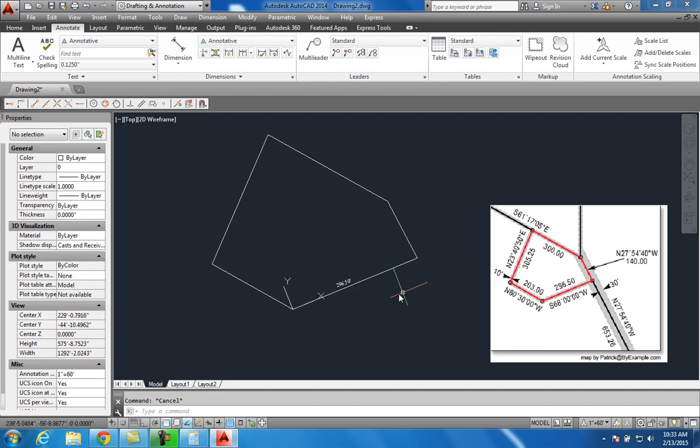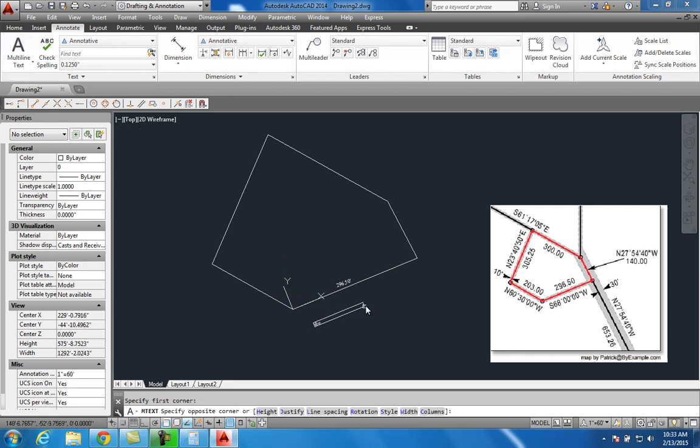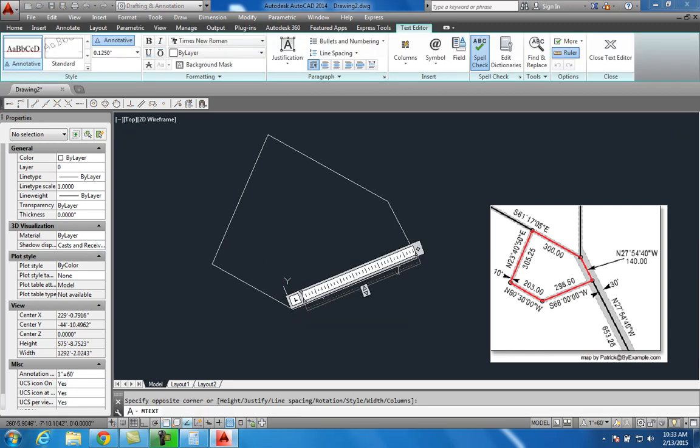And then I could do the same thing. You do multi-line or single line text, it doesn't matter. You come down here just underneath of it. Whenever you use single line text, that might be another good way, but I just want to show you that UCS, when you use multi-line, it'll follow that. And underneath of it I'd hit caps lock, S for south.